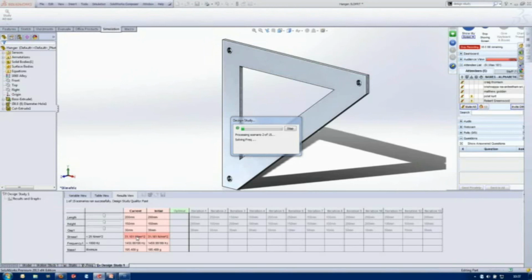They don't require any form of simulation. The optimization studies tend to be used with the simulation results, and what happens is they allow you to put in a series of information. Doesn't have to be discrete steps for optimization studies, and then it will take your parameter values over a number of iterations, and it will rerun the simulation studies for each of those, assume you've got them listed as constraint, and then it will give you a goal as an output.